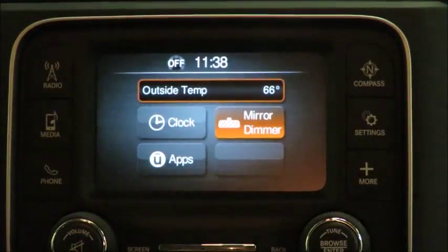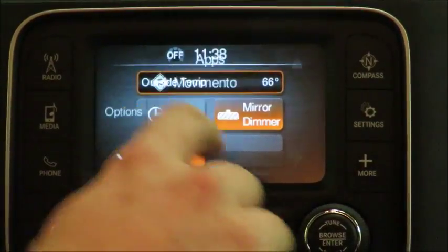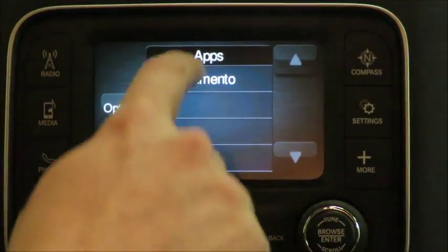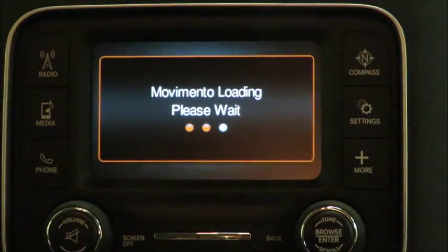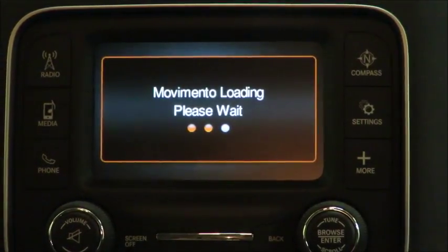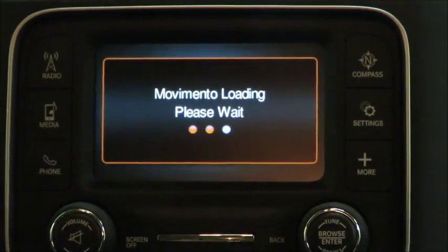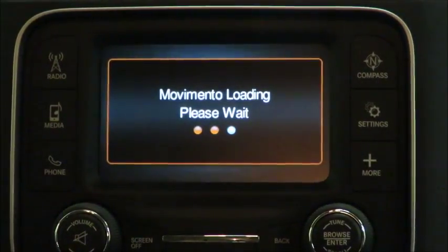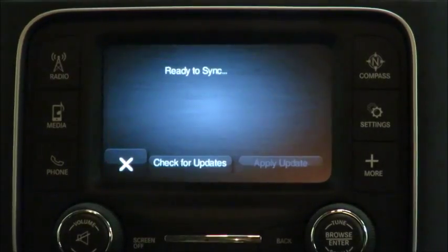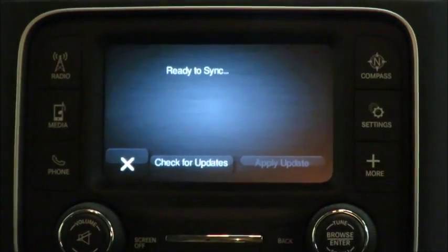It appears as an integrated Uconnect application. The application will only control and display the progress of the OTA event. In the future, the OTA client software itself could be ported to the head unit to perform a self-update, as well as the entire vehicle through its connections on the vehicle networks.